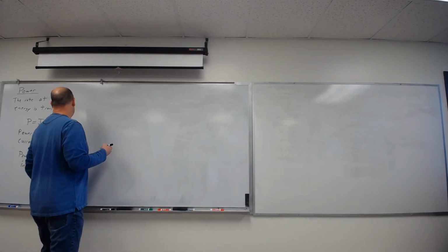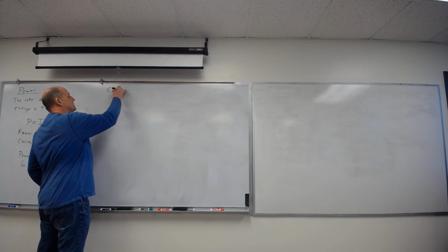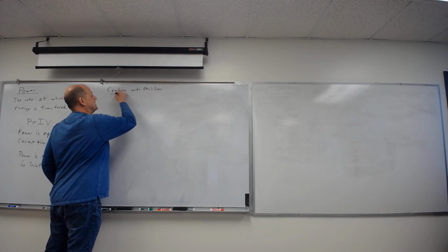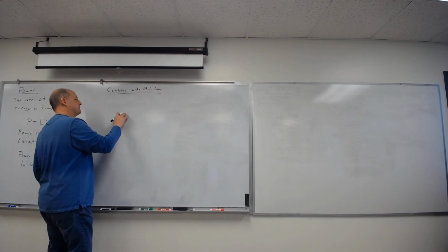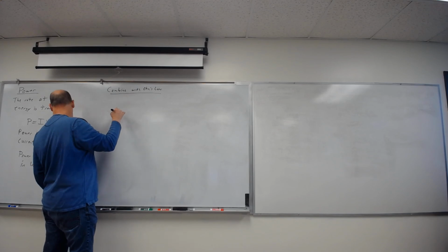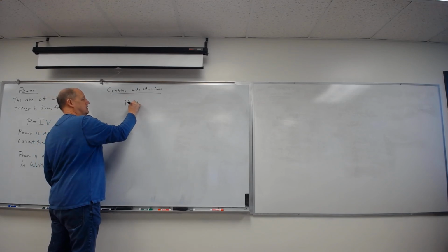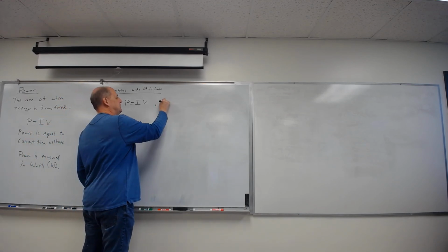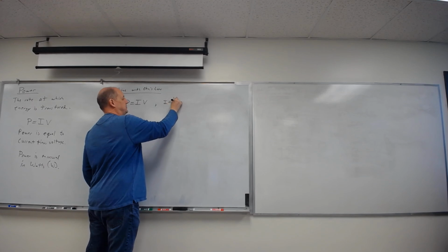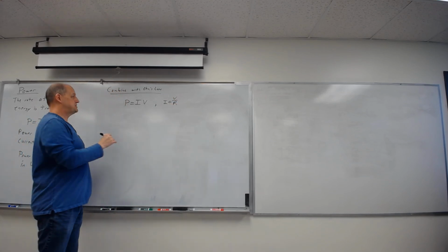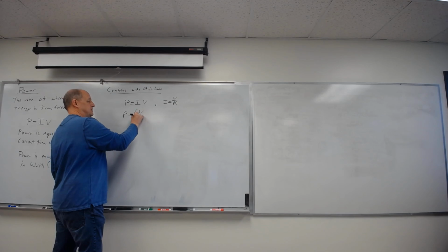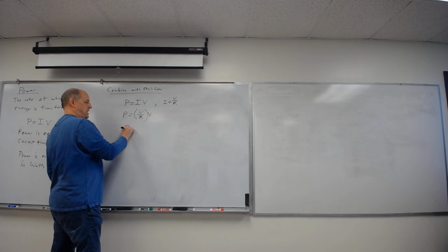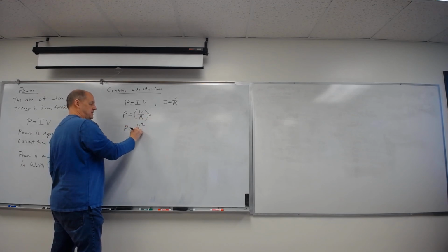Now what I can do is I can combine this with my Ohm's law. This is some of the homework here this week too. So I know that power is current times voltage. And I also know that current is voltage over resistance. So I can substitute voltage over resistance. So I just substitute this in for current. So power, V times V, is V squared over resistance.